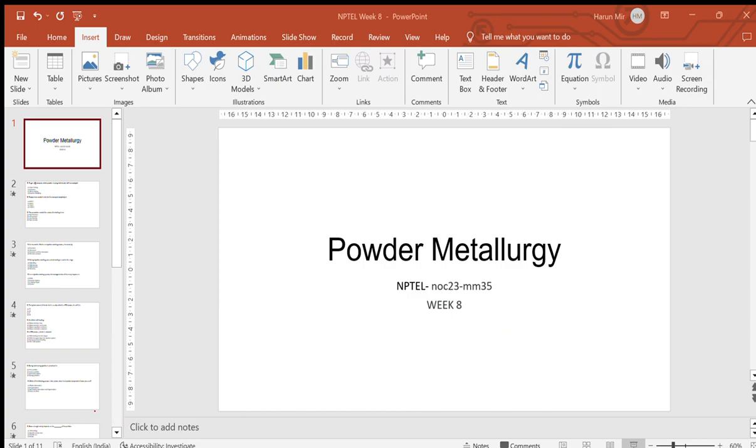But after mold ejection, we do not need the properties of the binder, because now we have compacted all our powders and we can remove the binder for further processing. So it is only after you have done all your compaction processes, whether it is feeding, injection molding, or cooling, that you will remove the binder. So the right option for binder removal is after you have injected the mold. So option D is right.